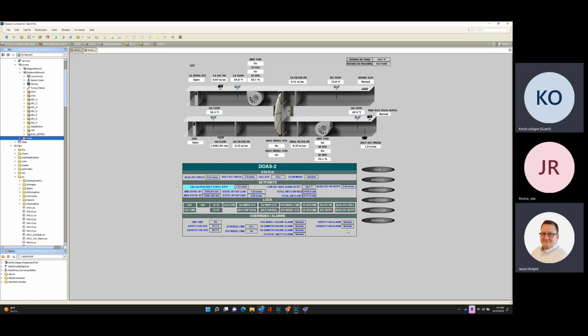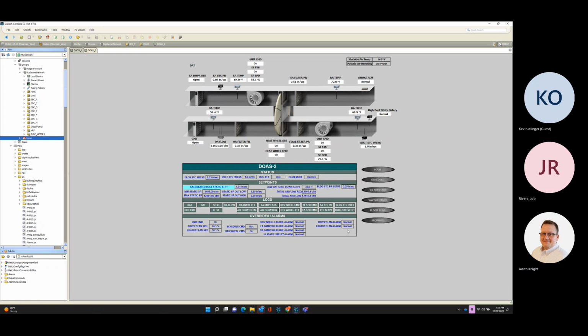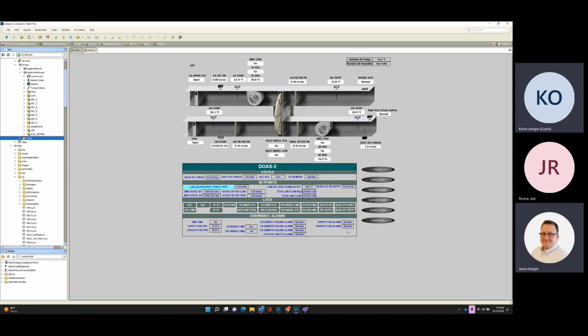Now, last week we had a DC under voltage alarm on several units. And you'll see that on the graphic, it was just into alarm. Or the fan was in alarm, commanded on and the status was not running, excuse me. But yeah, at that point, you'll have to go up to the roof, check the unit to determine if it's an ECM or if it's a VFD.